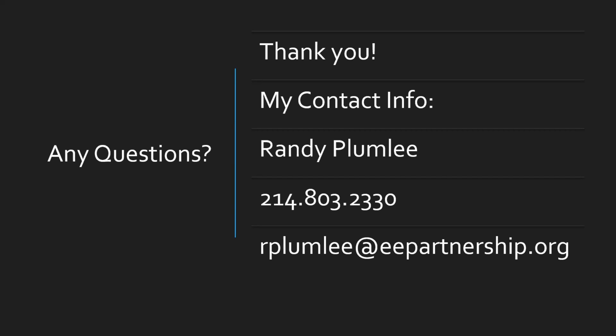That's a great question. It comes down to the existing side of the code, chapter 5. If it's going to be a new addition and it's new equipment, then it should follow the energy code. So just because it's an addition, if it's greater than 25,000 square feet, it should be required to have energy monitoring. But if it's tied into the original system, like they're adding additional ductwork, but some of the systems are still heating and cooling another part of the building that's original, and it's sized properly and you can use some of that HVAC, if you don't change it out, it doesn't have to adhere to code.